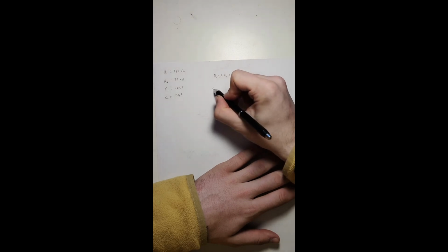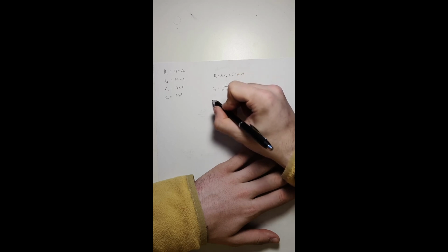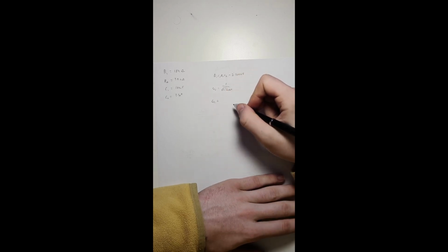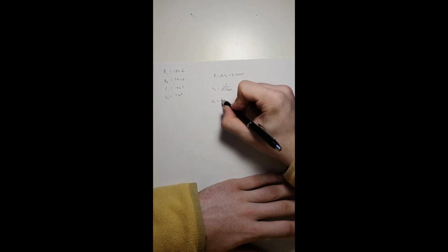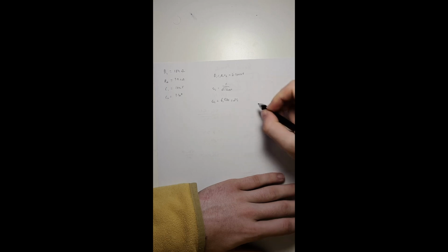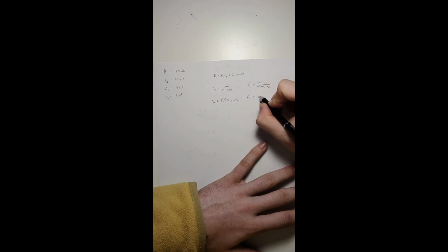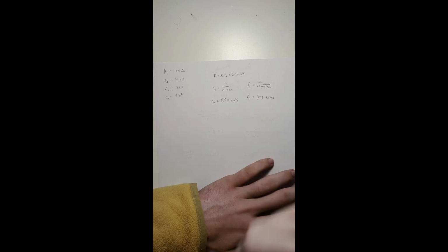So then we know that omega C is equal to 1 over the square root of 2.32 by 10 to the minus 8. So omega C is equal to 6,570 radians per second. The cutoff frequency in terms of hertz is 1 over 2 pi root R1 C1 R2 C2. So then that's going to be equal to 45.67 hertz.